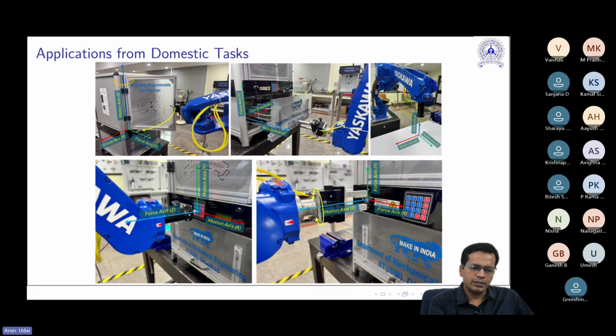Next, you see there are four different instances when the motion is constrained. First one, this one is opening a door, in which you have a constraint, like you have an axis about which you can rotate, right? If your robot is not compliant, that means it cannot take up any forces due to any error in the calculated trajectory. So it has to go in this trajectory, but if there is any collision or any inaccuracy in the calculated trajectory, it will break the door or door handle or the hinges, right? So it should take care of any interaction forces due to any error.